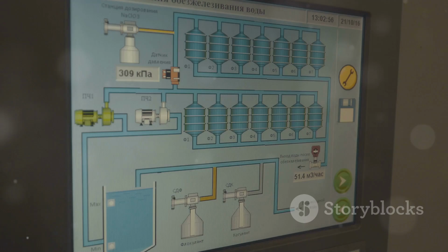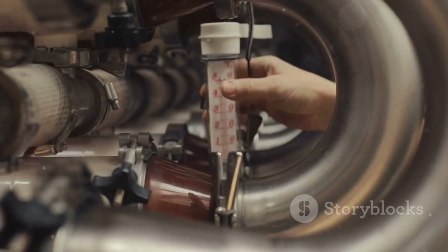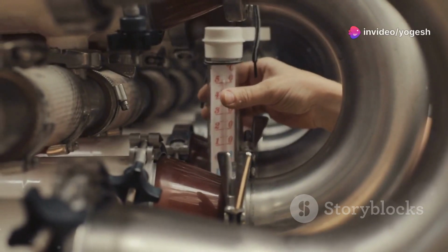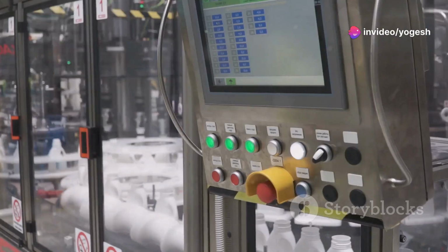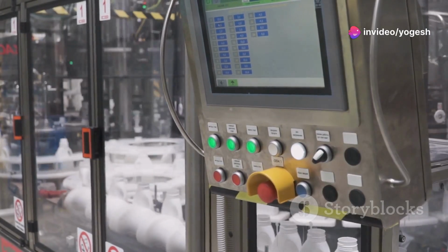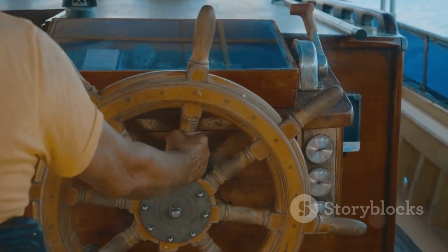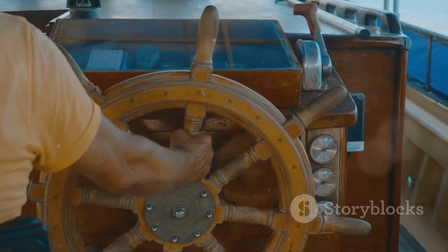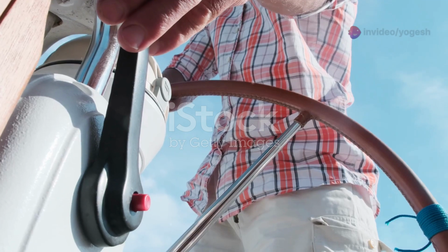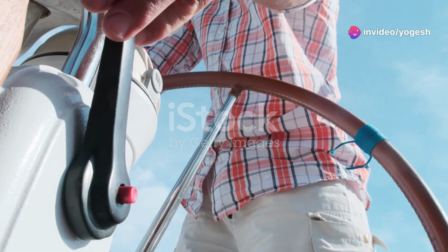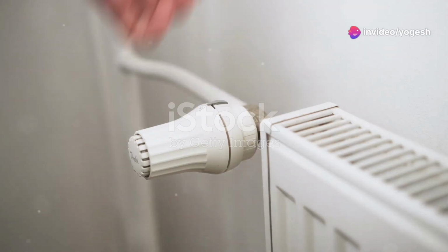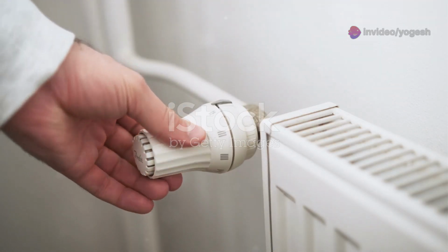So, a bigger error means a bigger response. A smaller error means a smaller response. It's quite straightforward, really. This provides the primary driving force for correction. Imagine you are steering a boat towards a dock. If you are far off course, a big error, you make a big turn. If you are only slightly off course, a small error, you make a small turn. That is how the proportional controller works.